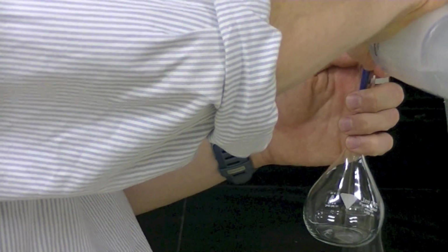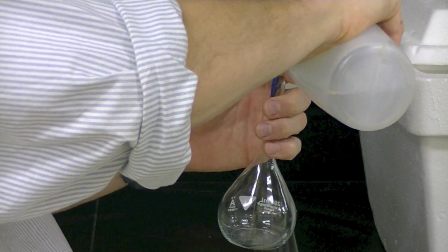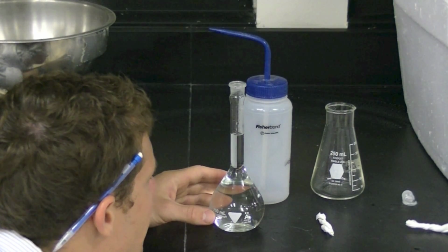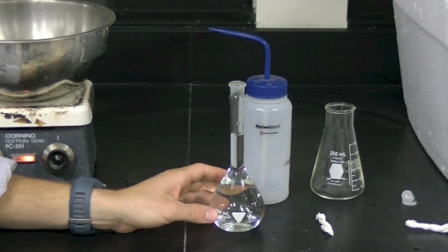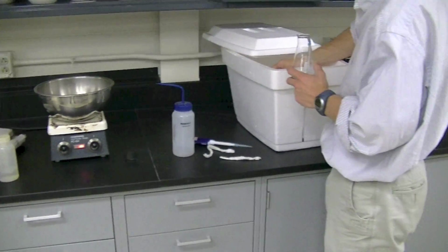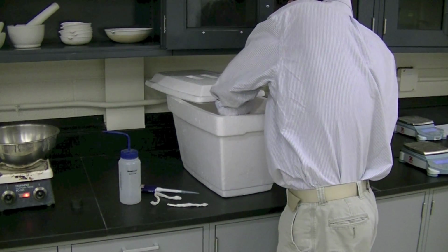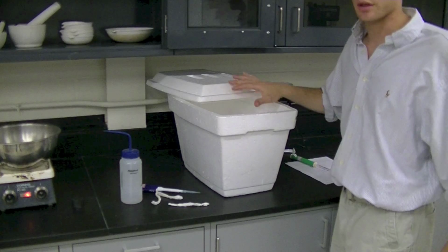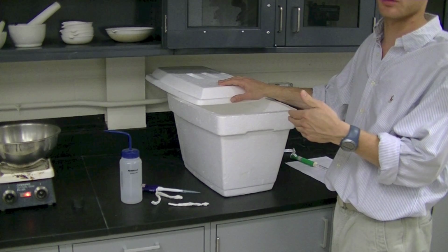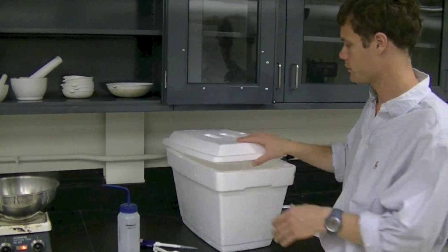The second stage of the pycnometer calibration entails calibrating the volume of the pycnometer. First, fill the pycnometer with de-aired water to either above or below the calibration mark. Place the full pycnometer in an insulated container and allow at least 3 hours for thermal equilibrium to occur. Place more de-aired water and a thermometer in the insulated container. The equilibrium temperature should be within 4 degrees Celsius of room temperature and also between 15 degrees Celsius and 30 degrees Celsius.